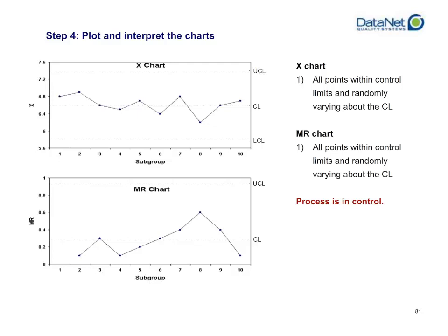And your MR chart, also all points are in control and seem to be randomly varying around the center line, which is exactly what you want. And this is a great example of why you want to actually use SPC rather than intuition. If you had begun tampering around and started trying to change your process for your pencil diameter around subgroup number 8, you might have shifted it adversely where you would push your process too far down, and you may have gotten some out of control points because naturally when this process was moving forward between subgroup number 4 and subgroup number 8, that was just some natural variation where it happened to be going up in 5 consecutive points and it came down naturally again.